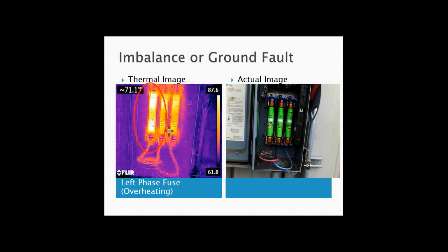After that same fuse blew, I performed a lockout-tagout procedure, removed the fuses, and I mega-ohmed each of the cables feeding that disconnect to ground. That test confirmed my assumption that I might have had a loose connection or a ground fault.